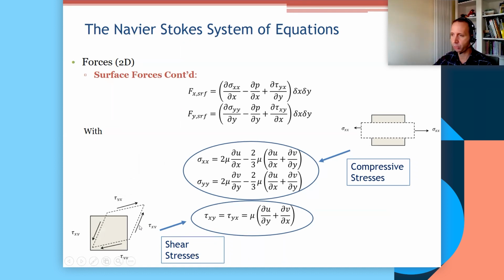So this one is the contribution here, and tau yx is the contribution here. There's a proof again of this symmetry, tau xy equal to tau yx. We can provide a proof which we don't give here. All I'm pointing out is that we have a definition for the stresses as a function of gradients in the velocity components, and that's the important point.